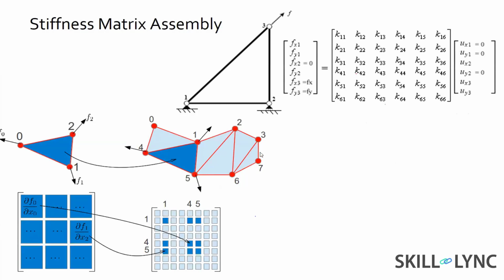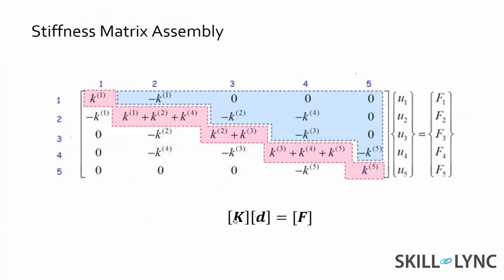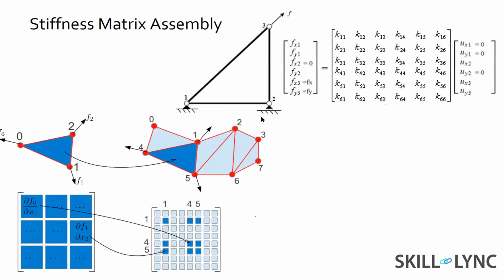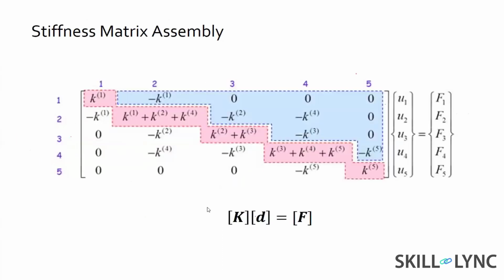And then if we have a bunch of elements, what we do is something called a stiffness matrix assembly. It goes like this: we know the positions of the displacements at each common point, and we add up the K1, K11, K12 constants here to derive the final global stiffness matrix. And once we have the global stiffness matrix, we again come back to the same Kx equals F equation. We invert the K to find the displacements and subsequently the strains and the stresses.